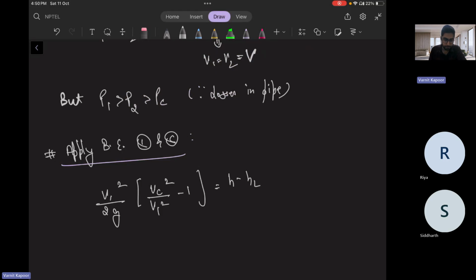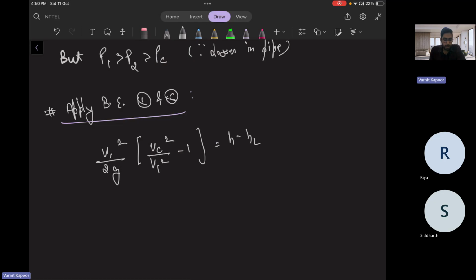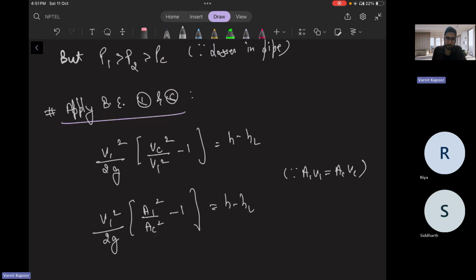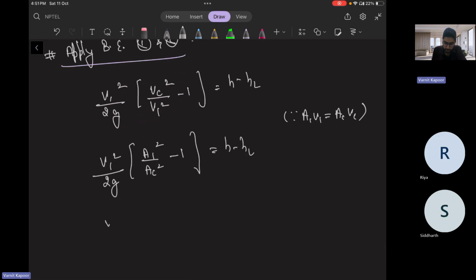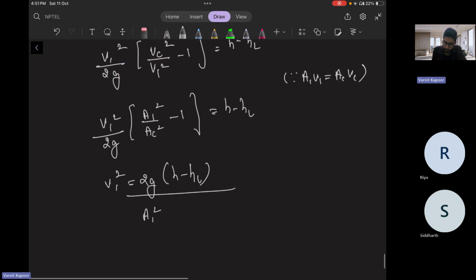Since we know that A1 V1 is equal to AC VC, you can write VC by V1 as A1 by AC, so V1 square by 2G into (A1 by AC square minus 1) is equal to H minus HL. So from here you will get your V1 square, that is 2G (H minus HL) over ...